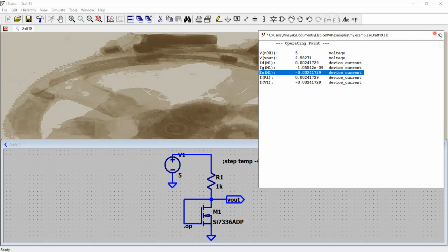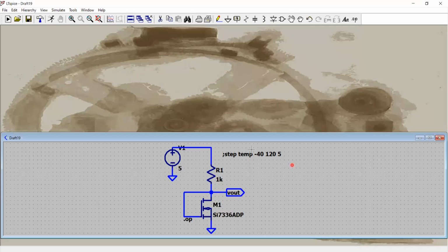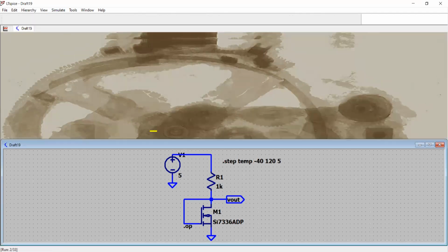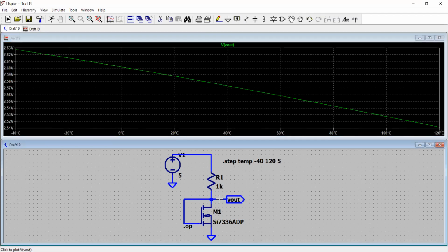All right, with that said, we can run the temperature analysis again by enabling this one. Just put a dot now, and we sweep the temperature and we plot this voltage like this. And this is how you get this value. Okay, so I hope you like this video, and just compare this with the previous session video, so you will get the behavior of the MOSFETs.